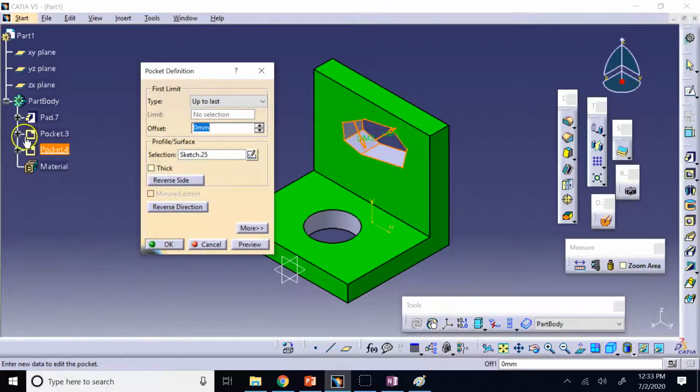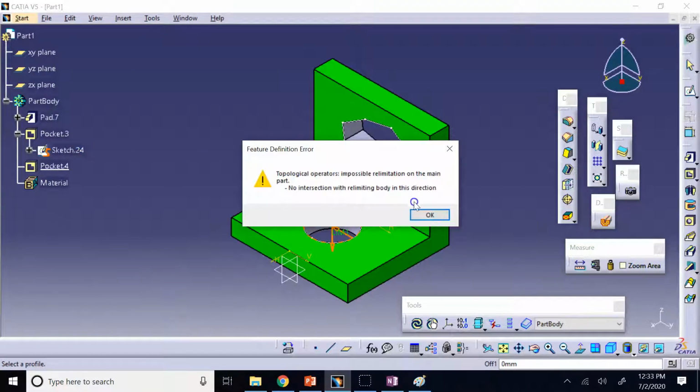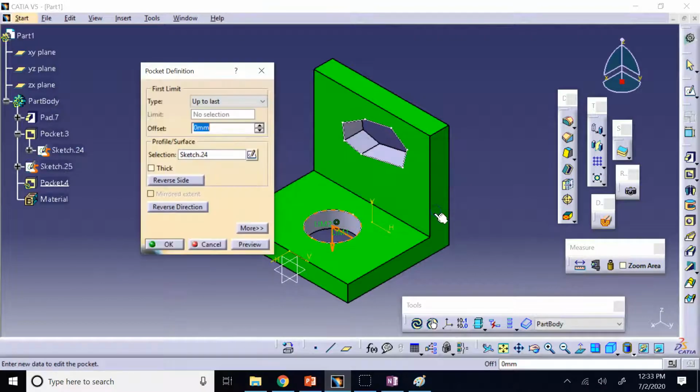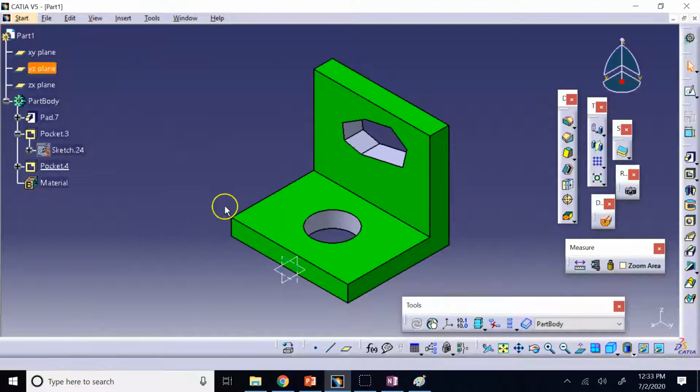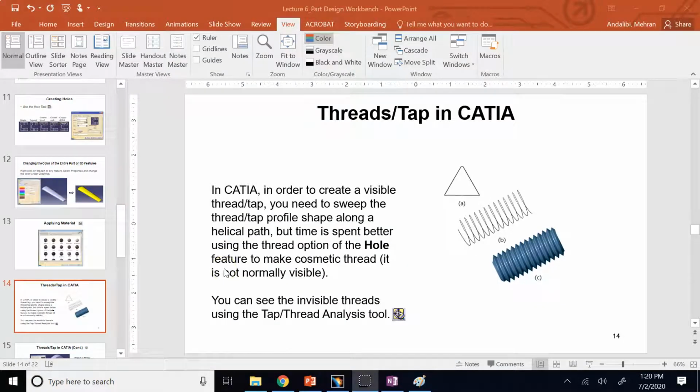So when I came here, now I can, if I want, click on that. If I go to the sketch, I can check this one instead. Of course, it is gonna mess it up in this case, but I can if I want to. Okay, so that's very important about reordering. So we have seen material, color, and so on. Reordering, changing the support plane for a sketch.